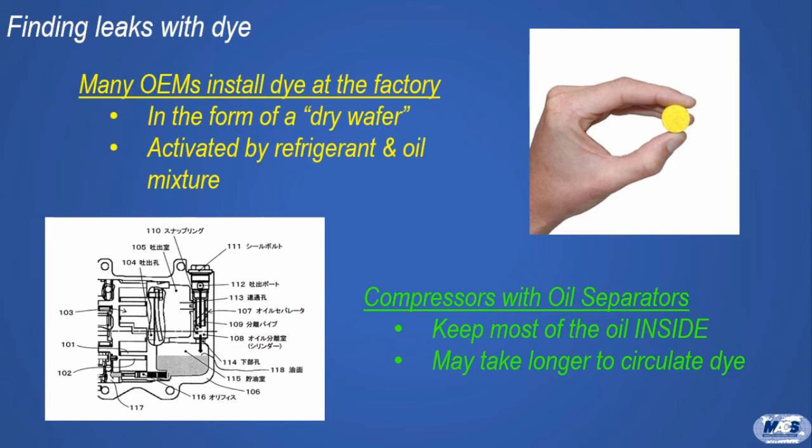And they also know that their real-world tests show that their compressors, whose oil separators are supposed to keep the oil within the pump mechanism, allow somewhat more oil through into refrigerant circulation than some rating they may have. So the trace dye works somewhat better than what might be expected.